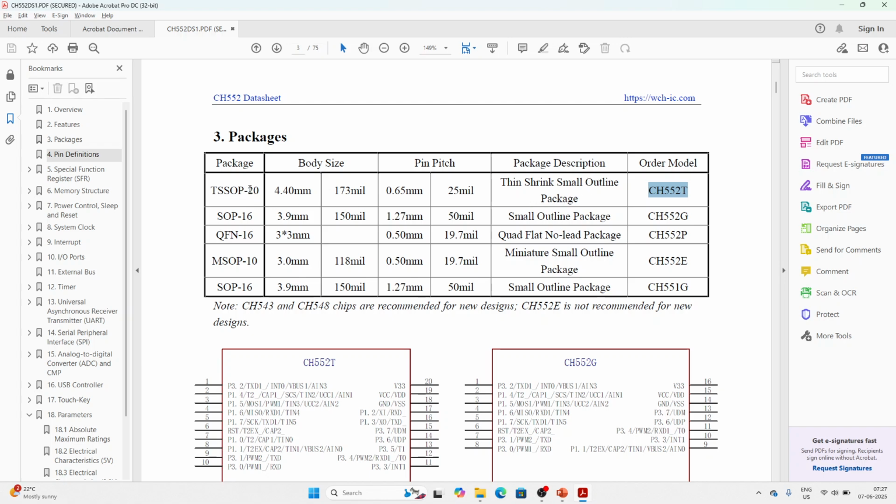It has 20 pins, out of which 2 are power pins and 1 is a ground pin. That makes it 17 pins exposed as GPIO pins. So 15 pins can be accessed as IO pins, leaving 2 USB pins. SOP16, which is generally common and is easier to solder.